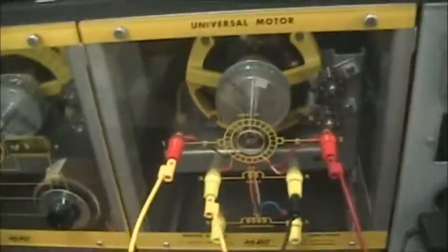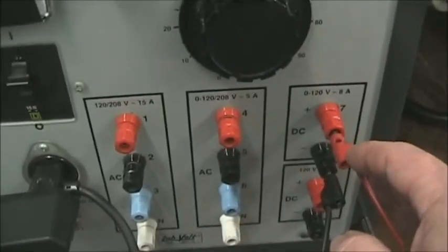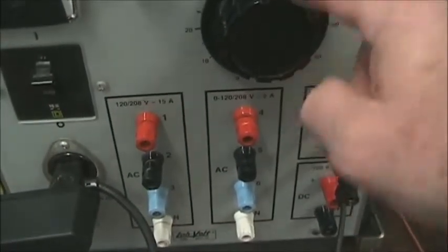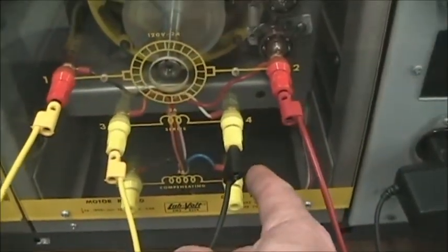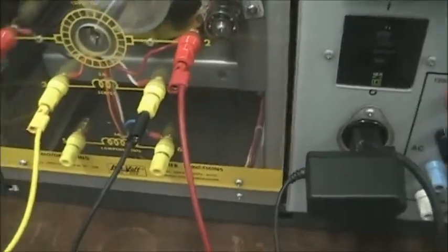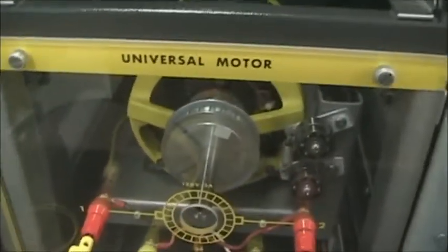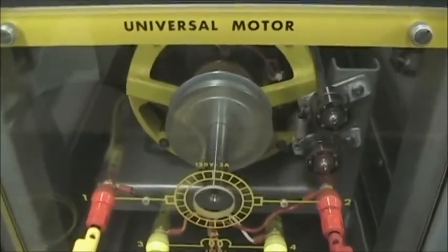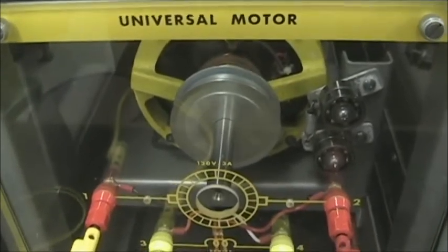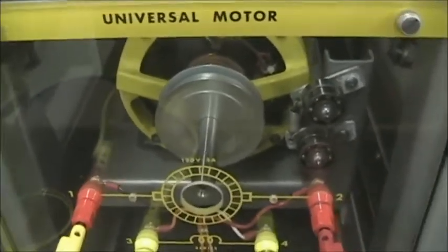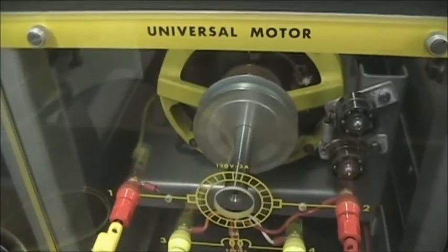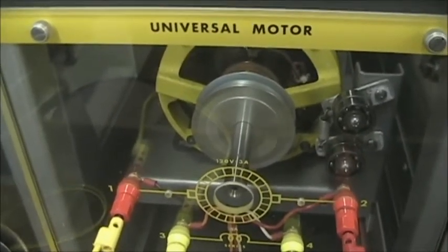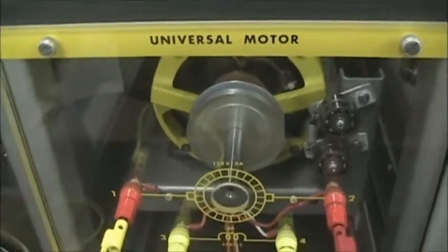So the wiring of the universal motor is pretty straightforward. I've got it set up for DC right now. I'll switch to AC. So I come off the variable DC, I pass through the winding, pass through the series connection, and then I return to, in this case, the negative. Energize the unit, and it spins up, right? Series motors run pretty fast at low torque levels, and of course there's nothing connected, so it's very low torque, and so it's going to be a much higher speed. There's some torque through the bearings, but that's it.